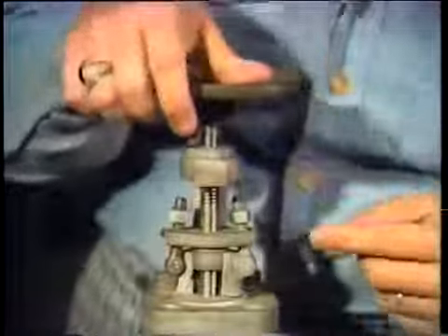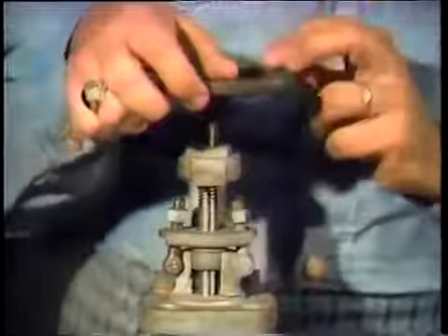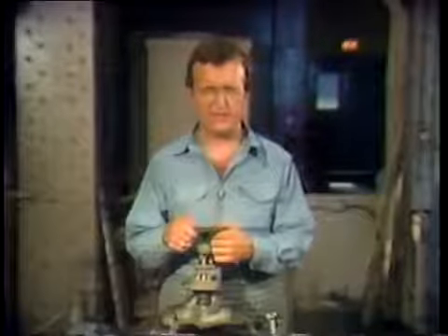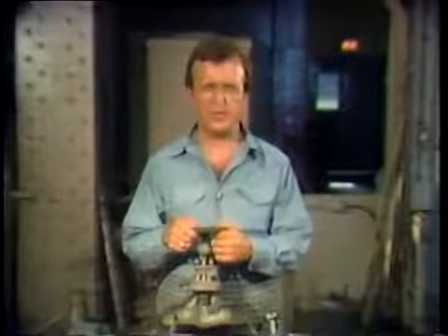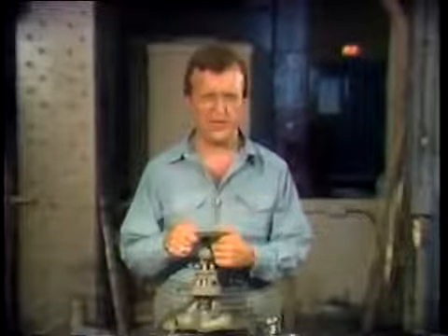Globe valves are usually made with a rising stem, similar to the rising stem of the gate valve. The stem is threaded into the bonnet or yoke bushing. Like gate valves, the specific function of a globe valve determines the material used to build it. You can find more information on the types of globe valves and how they're made in your text. The preceding types of valves are good for high pressure and high temperature. The following valves are used for low pressure, low temperature applications.